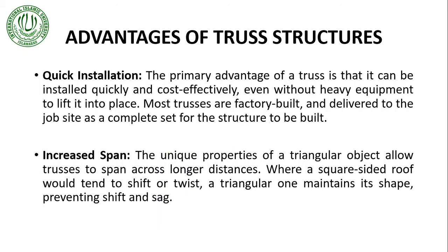Advantages of truss structures: first of all, very quick installation, and it's very cost effective at the same time because we do not use very heavy equipment to lift the truss into its place, and most of these trusses are factory built and they are delivered to the job site as a complete set, and then we just install these truss sets as they are to build the structure.